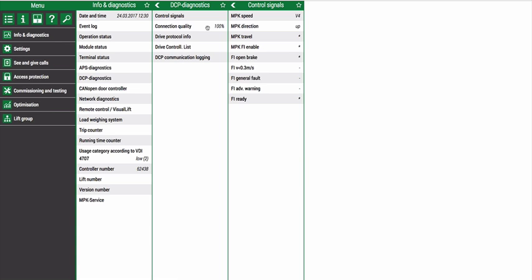This can be shown with the speed command as present set at V4 and next directional output coming on, which will then show you the travel, the condition of the brake and whether the speed is above 0.3 meters a second. Communication is always flowing between the two devices, but this is a good opportunity to make sure you can physically see any commands being present.